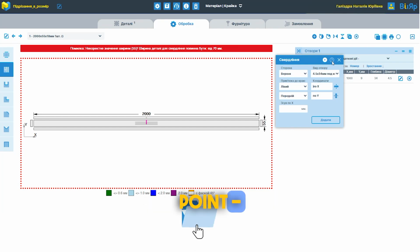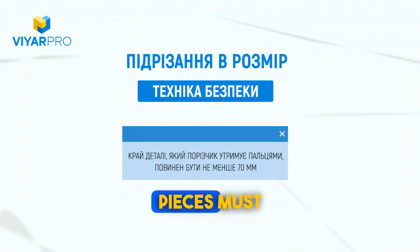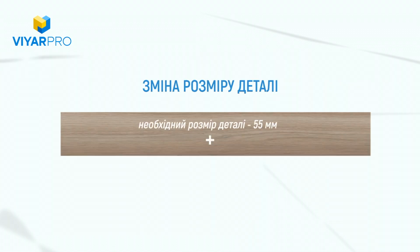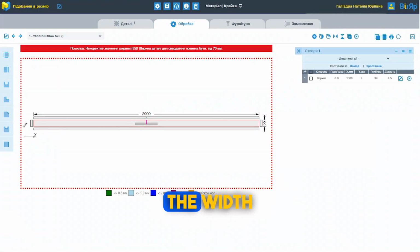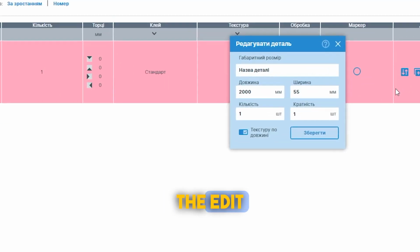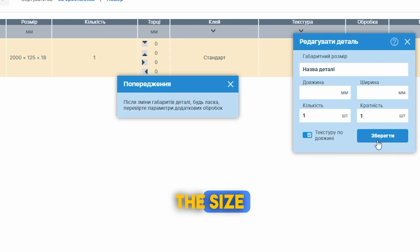An important point: according to safety rules, when trimming, the main thing is that one of the part pieces must be at least 70 mm so that it can be held in your hands, which means that you need to add another 70 mm to the required size of 55 mm. To do this, change the width of our part to 125 mm. Click on the Edit Part icon and specify the width value as plus 70. This makes it possible to avoid calculating the size yourself.